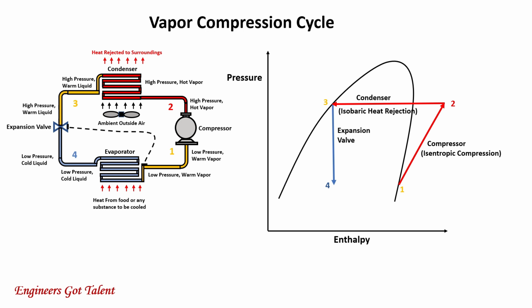The restriction at the valve removes pressure from the liquid refrigerant to allow vapor expansion. When the vapor expands, pressure and temperature drop significantly and the liquid changes its state from a liquid to a liquid-vapor mixture inside the curved line.